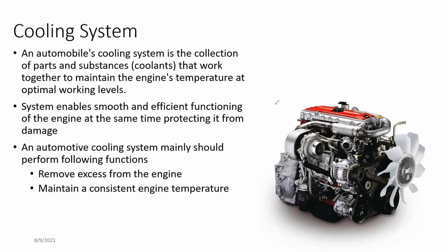The engine is going to seize because the engine coolant is not absorbing the heat from the engine. So all the components expand. That means the piston and the piston rings expand, and they get stuck in the cylinder itself. So the piston can't move. That will result in catastrophic damage. To avoid this, the cooling system has to take the heat away at all times.